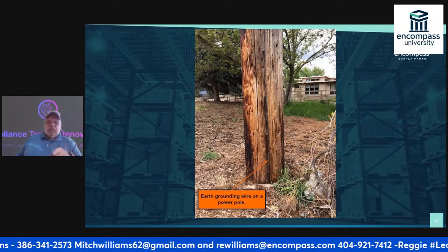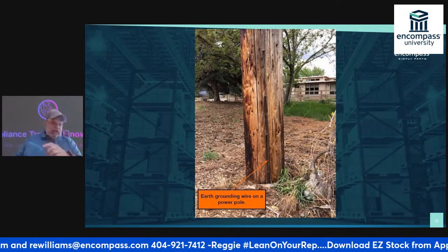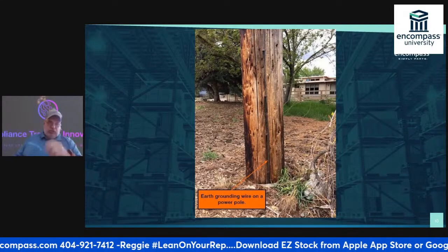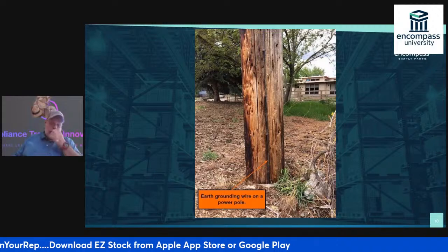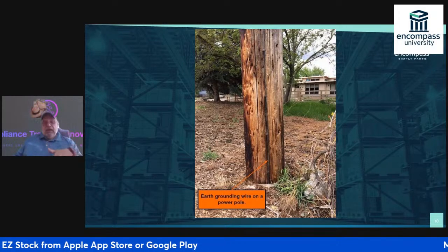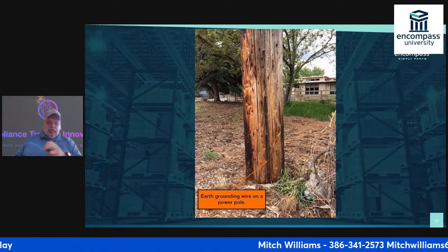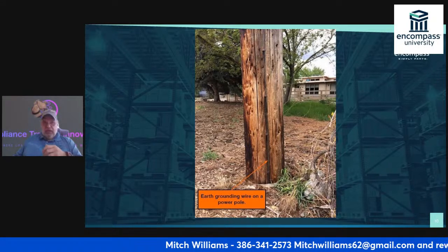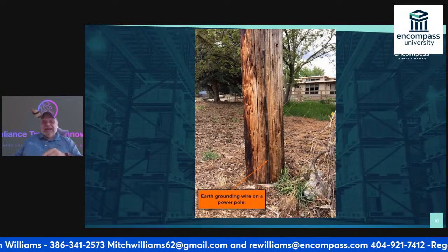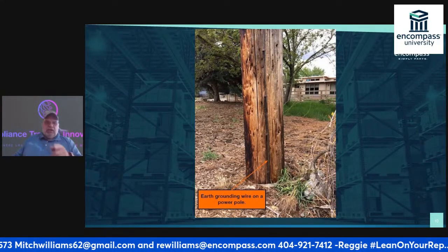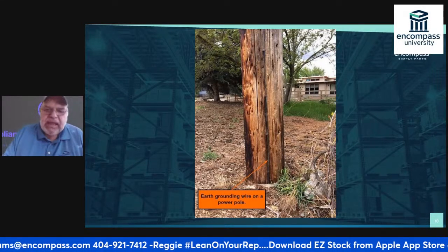That goes down into at least a 6, usually an 8-foot copper rod. Mine is copper, and I drive that into the ground. I can then tie that off with a copper connector. I will use that copper connector to tie my earth ground into my earth ground wire to complete the circuit so that I actually have an earth ground.